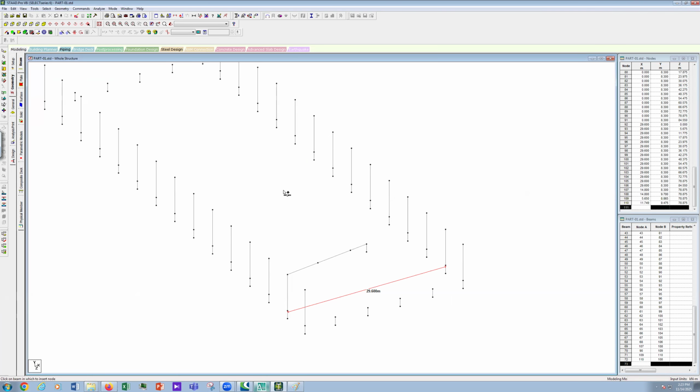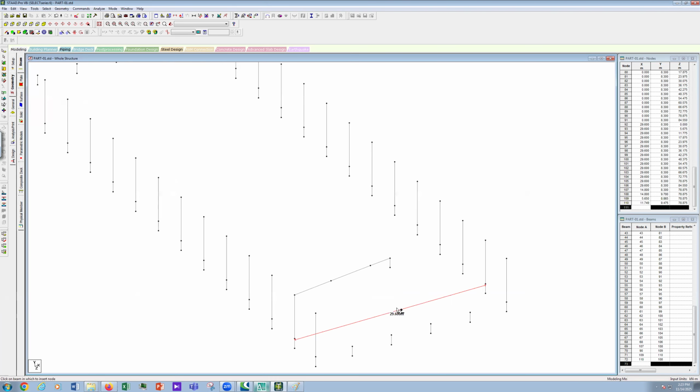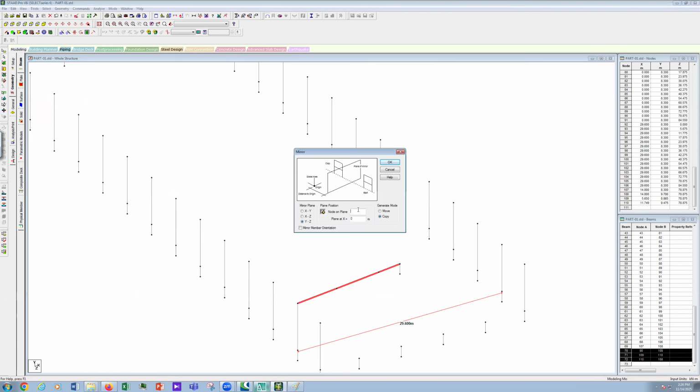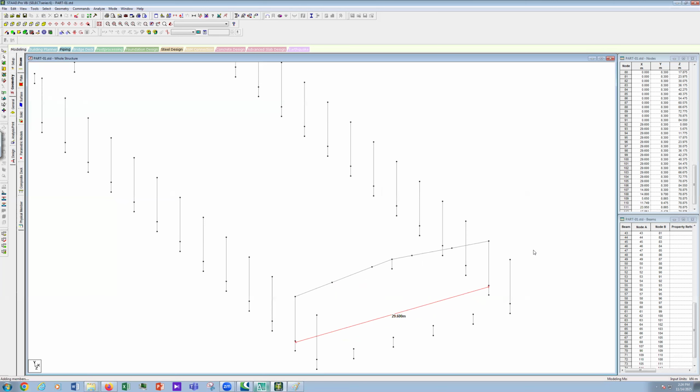Now, you can mirror it. Just look at this point. What is the number? 108. Then click this value, this one. And click mirror, YZ plane, no problem. 108 point. And then click OK. So here is the other part of the rafter.